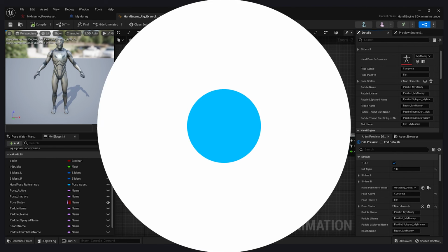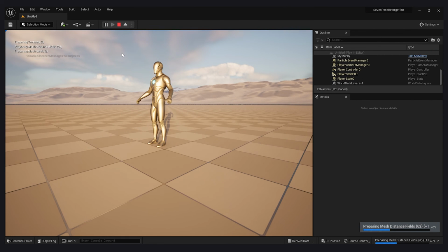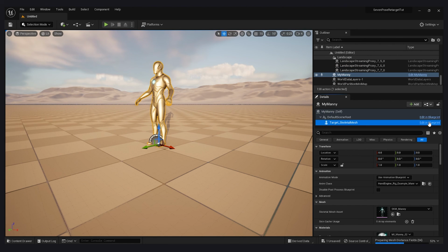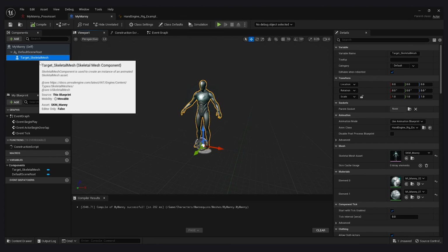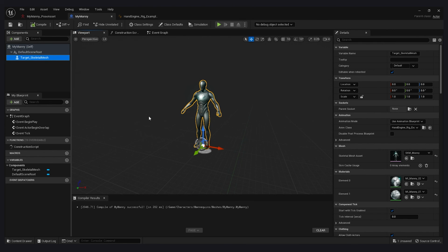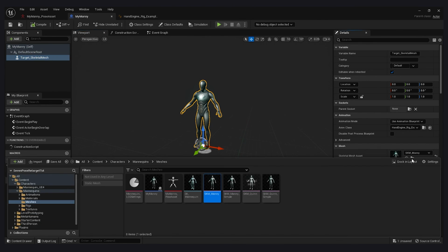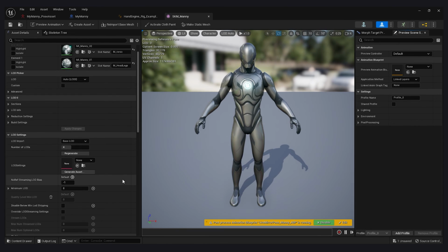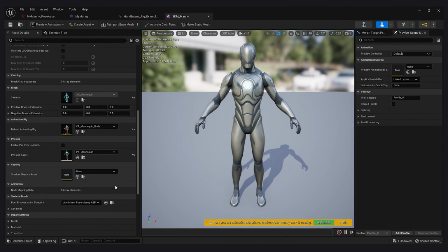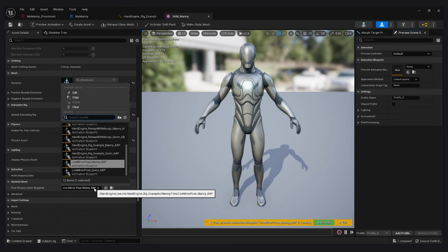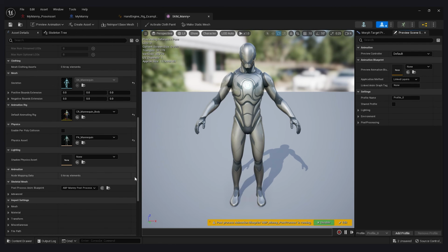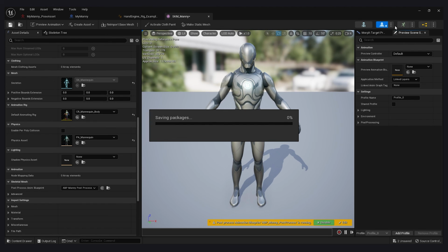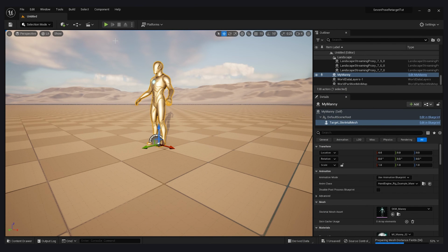So just a note, if your left hand is driving both the hands of your character, what we need to do is just navigate back to our skeletal mesh asset. And down here in the post-process animation blueprint where we have the live mirroring function, we just want to revert this back to the default. And once that is done, you can see that your left and right hand will be driving both hands separately.